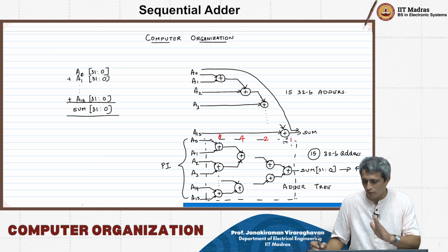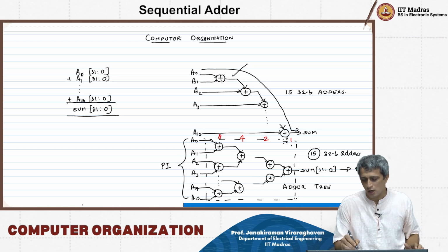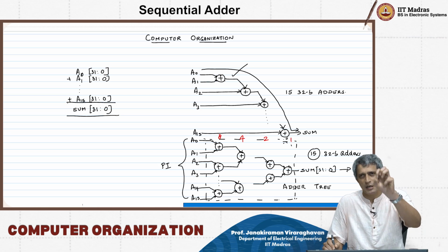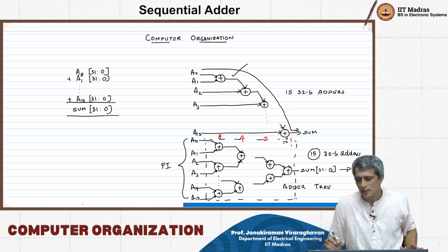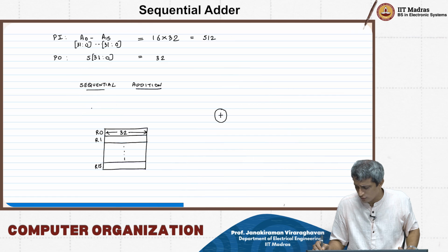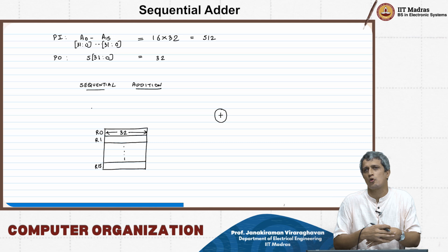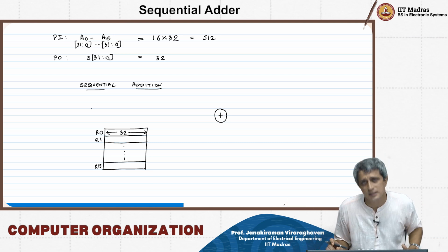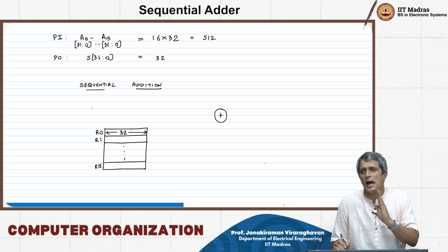So effectively what we are doing is this implementation, just that instead of having 15 separate adders, it's the same adder that we are going to use, get a partial product, add that to the next number and so on. We know that takes longer, and because it is sequential and controlled by a clock, it will take some integer number of clock cycles. We'll see how many clock cycles later. So I have an adder which is going to add numbers one by one from these registers.